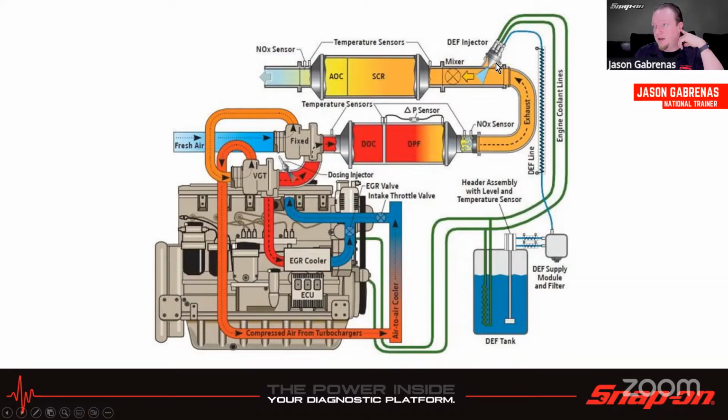The DEF injector, the diesel exhaust fluid, is going to be ahead of that SCR. And some vehicles have the SCR first, some vehicles have the DPF first. It just depends on how the manufacturer decides to do it. But with the DEF system, you're going to have engine coolant lines to cool it or warm it up, depending on the temperature outside. Supply module, filters, it could be an electric heater in there as well. Pressure lines, and then the actual injector itself. Then we have the SCR here, and then we might have a slip catalyst at the end.